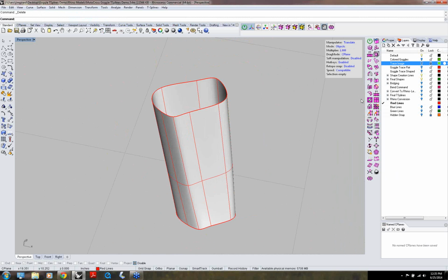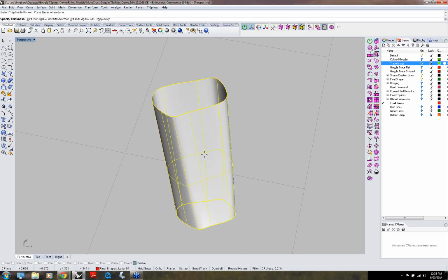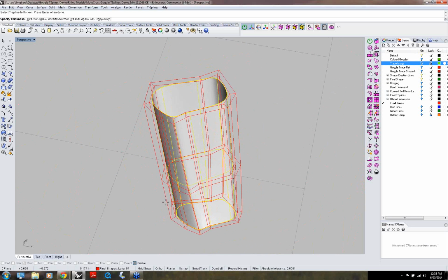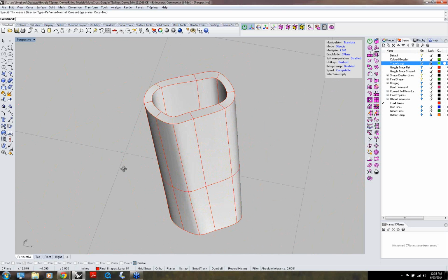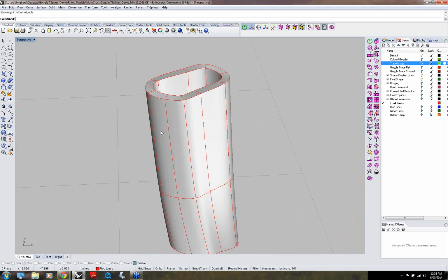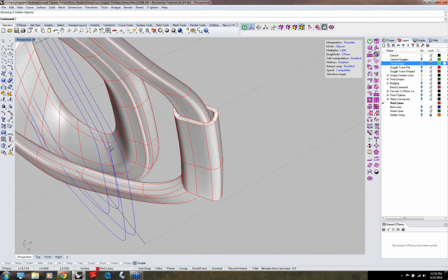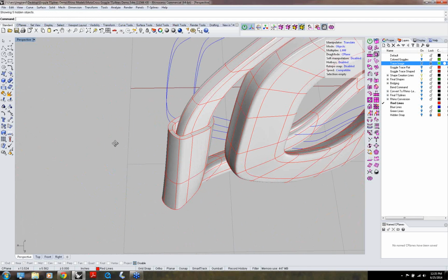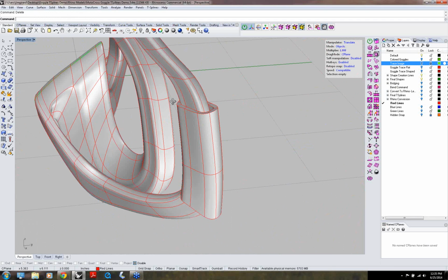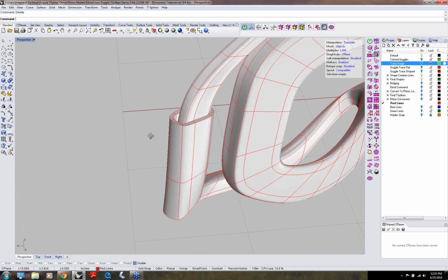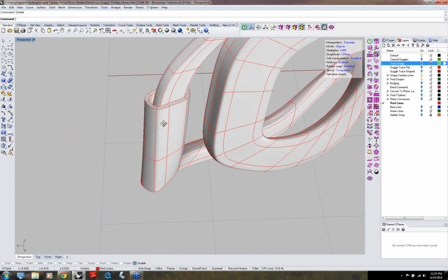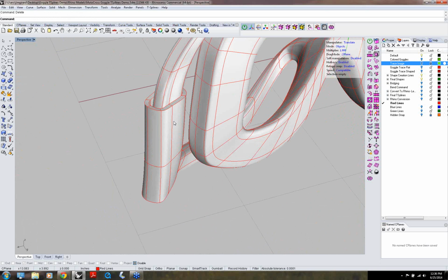And then I go ahead and I do the thicken command again. And take it to about there. Now when I bring in my old one, now you see where I've created a loop for the strap around here. And let me hide all my construction lines. Now, then what I do is I'll pick the face command again and paint, and I'll pick these and delete them.